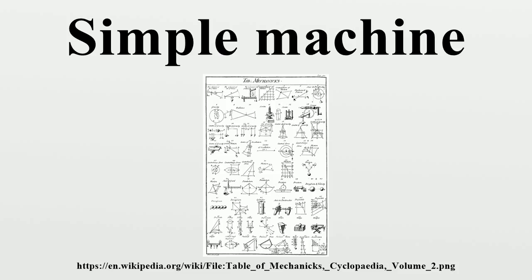A machine will be self-locking if and only if its efficiency η is below 50%. Whether a machine is self-locking depends on both the friction forces between its parts, and the distance ratio d_in/d_out. If both the friction and ideal mechanical advantage are high enough, it will self-lock.